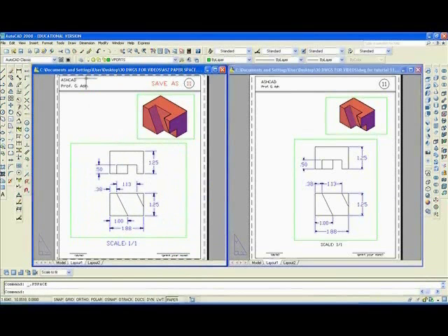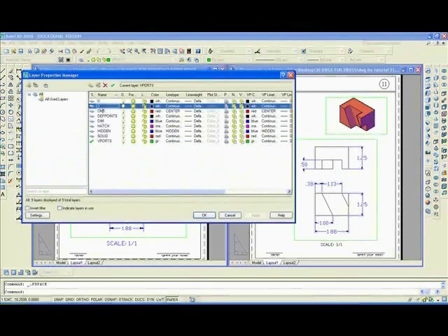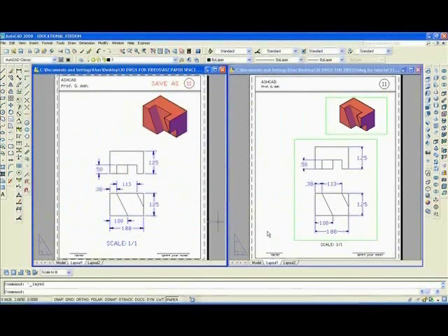and if you want to hide the viewport rectangle, you go to layer, make a different layer current like 1, and freeze the viewport layer. The drawing is now complete and it looks correct in all respects. So this is the end of tutorial 11.